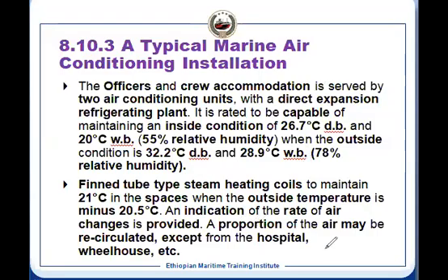So in this case also, since air is getting the temperature, we use the fin tube type heat exchanger. It means this is the tube, and there will be a number of fins attached to this tube, so that the surface area is increased. So this is called extended surface area, and it will give a very good effect because in all directions the heat will be transferred. Three directions, heat will be transferred through the fins. So it increases the heat transfer coefficient or the efficiency of heat transfer.